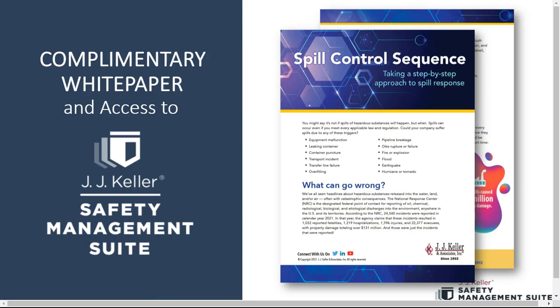The EPA defines a point source as, and I'm going to quote this, a discernible, confined, and discrete conveyance, including but not limited to any pipe, ditch, channel, tunnel, conduit, well, discrete fissure, container, rolling stock, concentrated animal feeding operation, landfill leachate collection system, vessel or other floating craft from which pollutants are or may be discharged. And that's the end of the quote, and that's from 40 CFR 122.2. So think of a point source as pollution discharging from one place or one identifiable point.